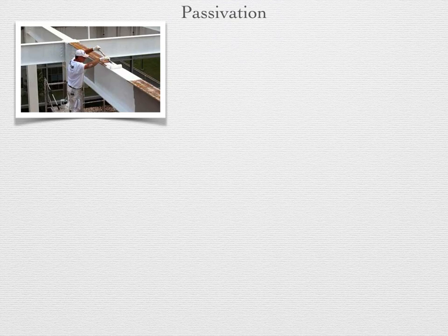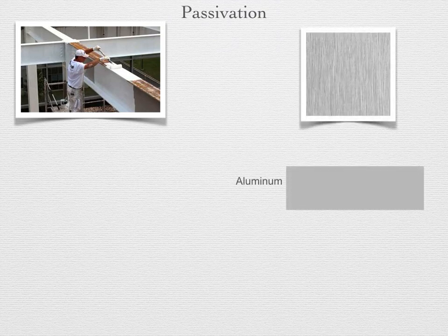In some cases, the corrosion products themselves can become a passivating layer. A freshly cut surface of aluminum, for instance, reacts quickly with atmospheric reagents to form a layer of aluminum oxide, Al2O3. It becomes a stable layer a few nanometers thick and is bound strongly to the underlying aluminum crystal lattice. It becomes a barrier to further oxidation of the aluminum.